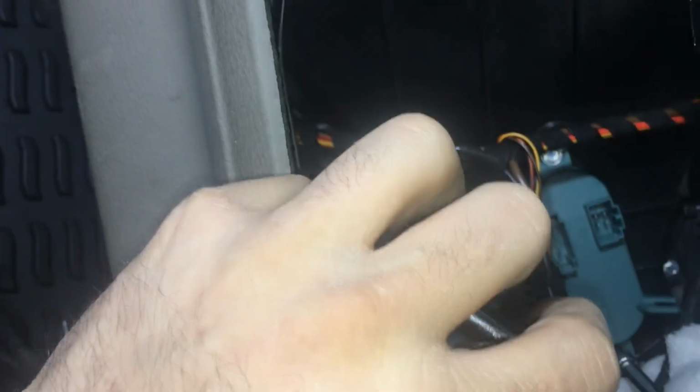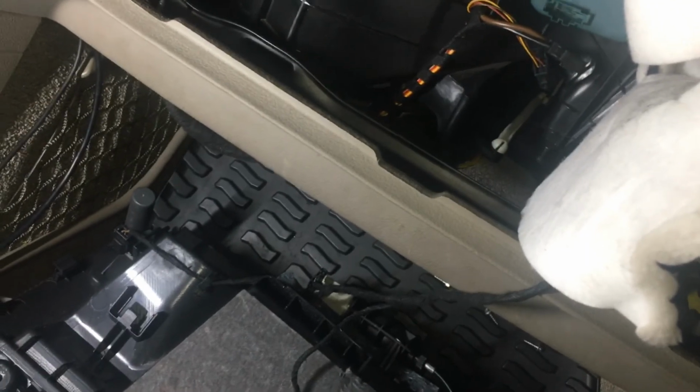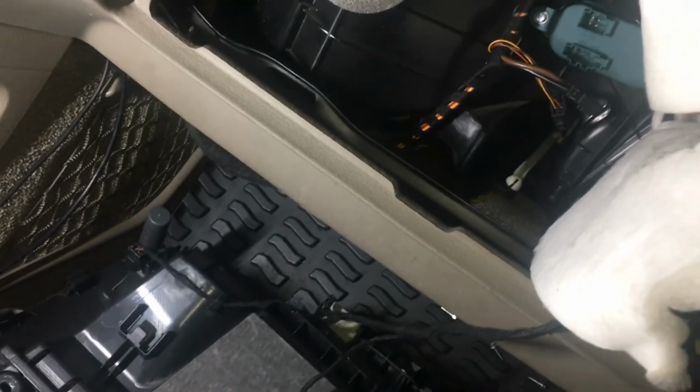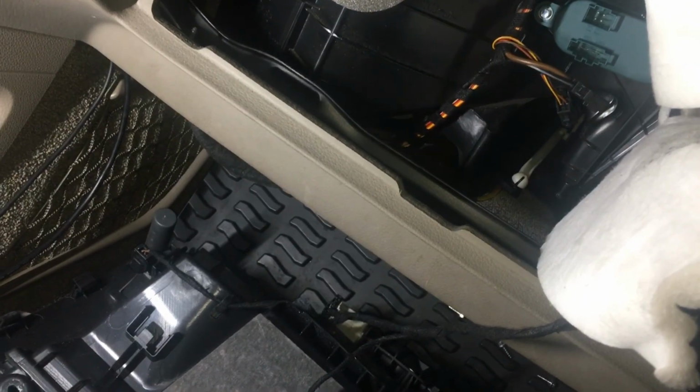VCDS was showing no voltage when it was trying to call the fan to spin, and when I tested it, the fan went to 0 volts when it tried to spin it. Testing the fan externally, it spun, but it was frying the wires. So I don't know if my fan motor is actually going bad and it draws way too much current. I don't remember if I videotaped that or not, but I'll probably have it before this. When I connect the factory fan up to a 12-volt battery, I have low gauge wires and they start to burn up almost instantly. So that thing is drawing a lot more current.